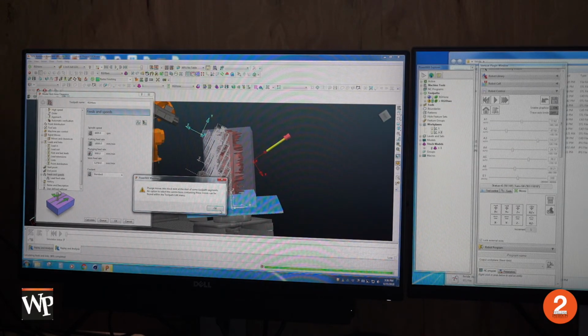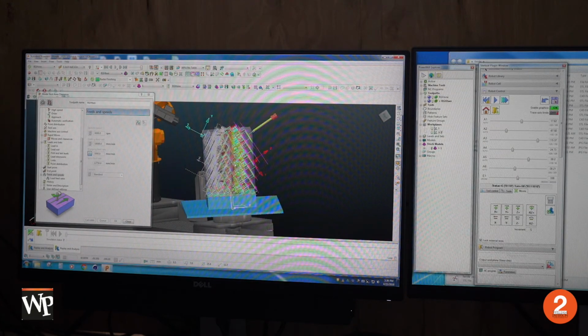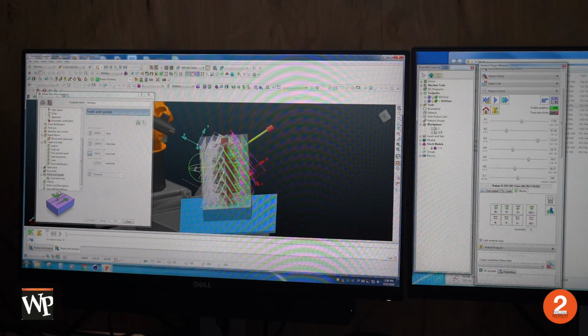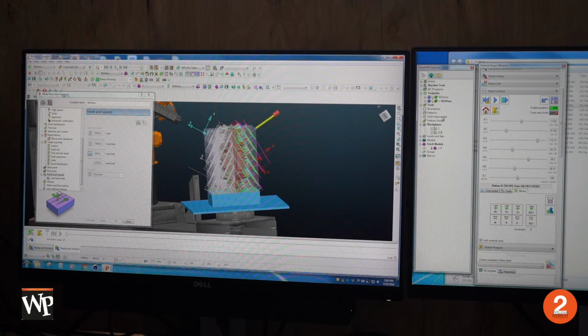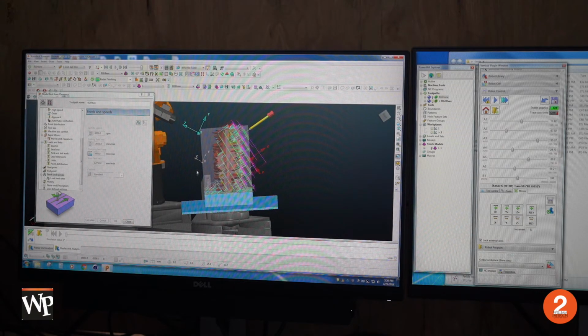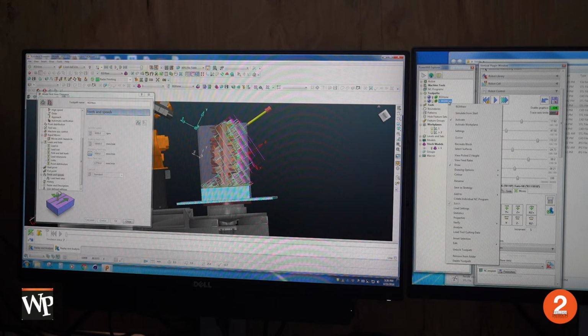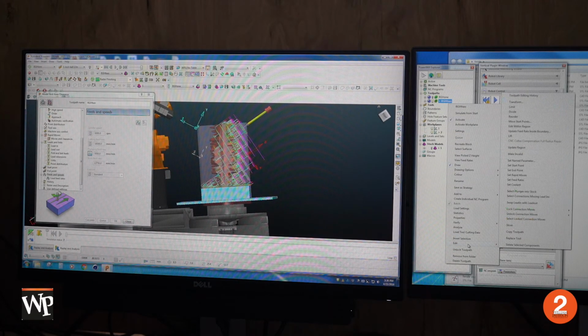Okay, so I'm going to click OK. So I'm going to hide our first toolpath. We're going to have to limit this toolpath again. We're going to have issues reaching this far. So we're going to right click on RGH2, edit, limit.